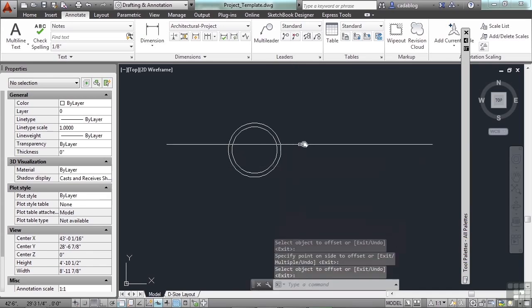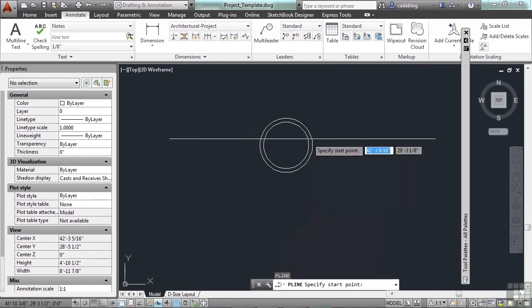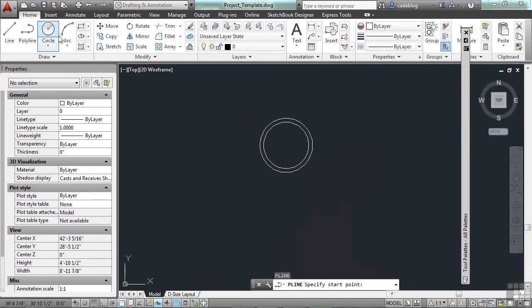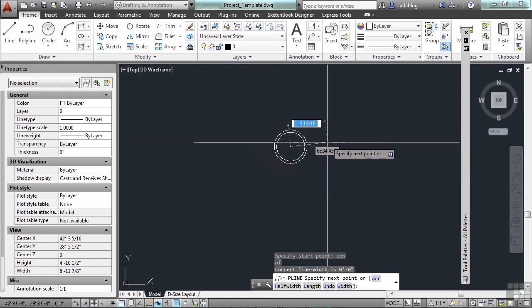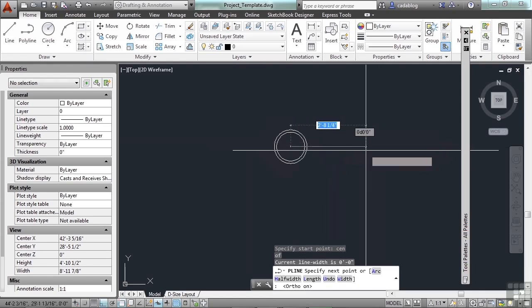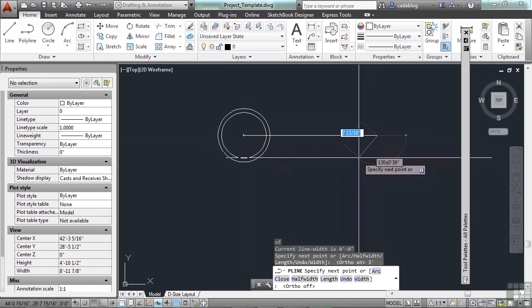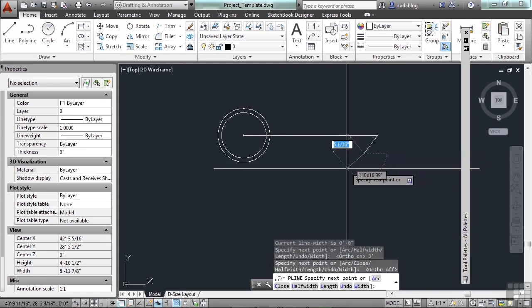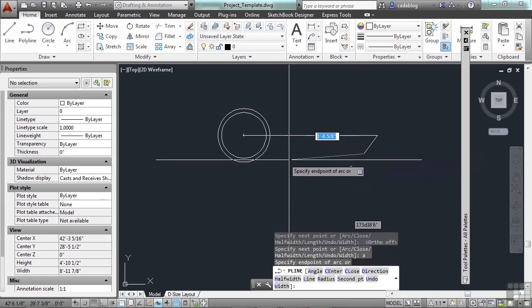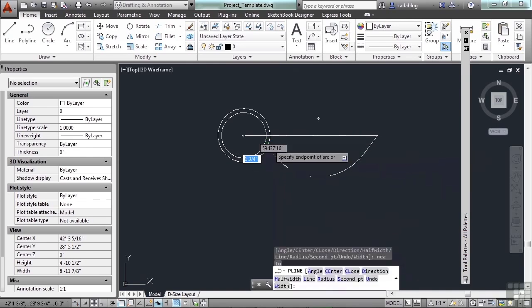There we go. Now let's draw a polyline from the center. Type in PL for polyline, or you can get all these commands up here in the Home tab in the ribbon. Start it from the center, hit F8 to go straight out. Let's go 3 feet. Turn off the ortho again, and just draw a short line, say 6 units, just about anywhere. Hit A for arc. Type in NEA for near, and we're going to drop it in right there.